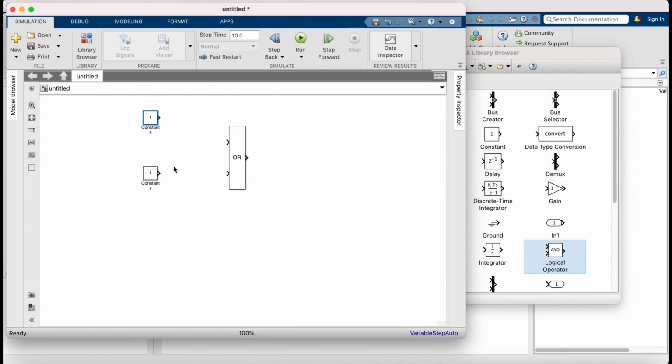Now here's how this stuff works. If I've got a block out here, you can join the arrow, and generally it will only allow you to join arrows where an output is going to an input. As we start lining up inputs and outputs, Simulink will give you suggestions. You can click on this and it'll join. Another way to do this is click on the origin block, and this is the destination block. So press your control or command key and click on the destination block. Okay, do that again for this one.